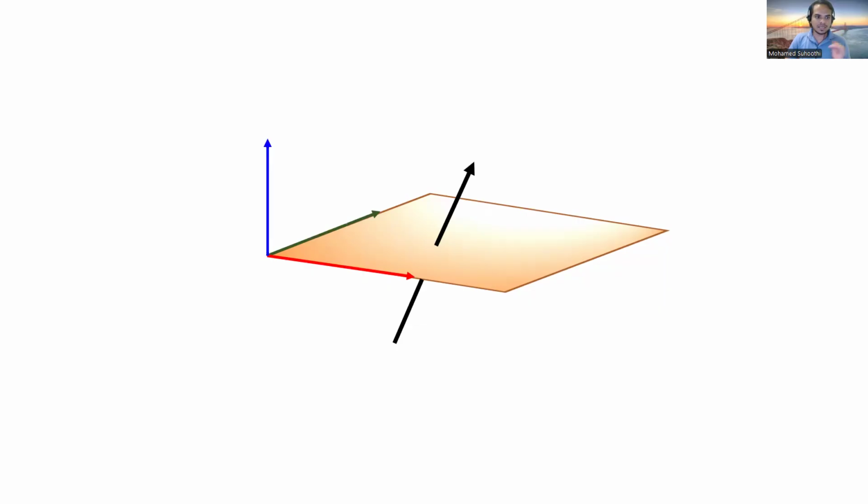So let me decompose this force. One, the vertical, that means perpendicular to this plane. This is actually parallel to my z-axis. Therefore, if I divide by the area and convert it into stress, then I will get my sigma z component, right?